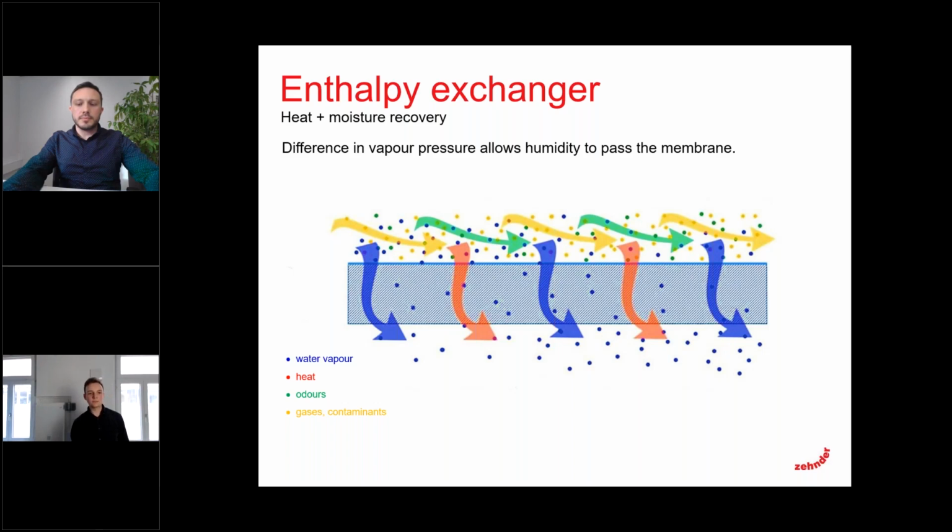And additionally, a standard heat exchanger can only be driven till 0 degrees. An enthalpy exchanger can operate in a normal mode till -5 degrees because there's no risk of freezing. What happens below -5 degrees? That's what I want to show you now.